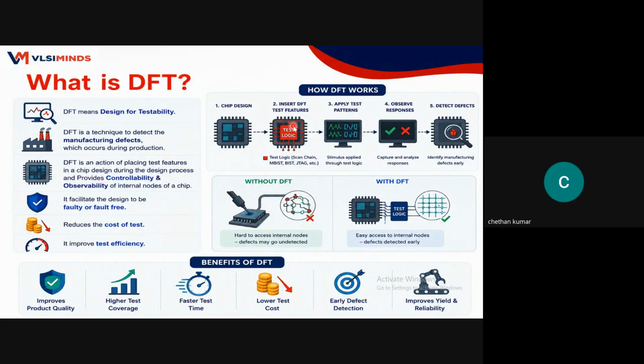Once the RTL level is completed, it comes to a synthesis team. They synthesize it, that means they convert the RTL into gate level. That gate-level netlist is taken as an input, and then we do the scan insertion. Scan insertion is just stitching all the flip-flops in the design like shift registers to have controllability and observability.